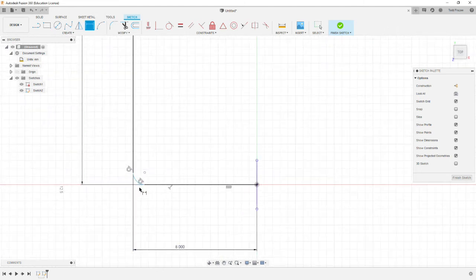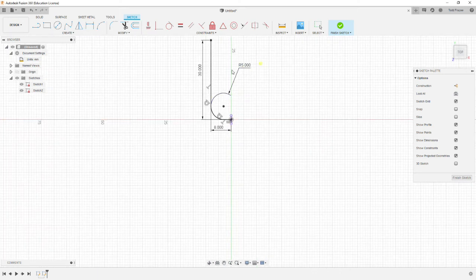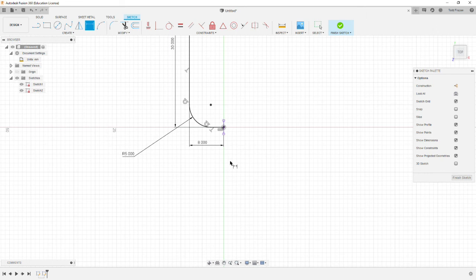Now our fillet here, our radius, they give us an inside radius of the outside of the tube of being 3.5. We're offsetting to the center line of the tube, so in this case we need to add 1.5 to our value. So we're going to put a dimension on it, and 3.5 plus 1.5 should be 5 millimeters. Alright, and we'll select Finish Sketch.